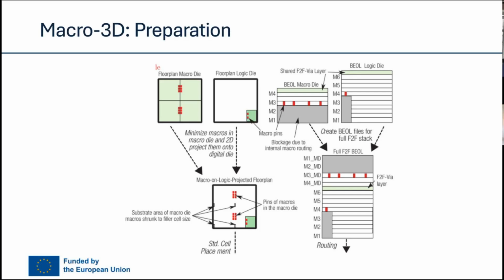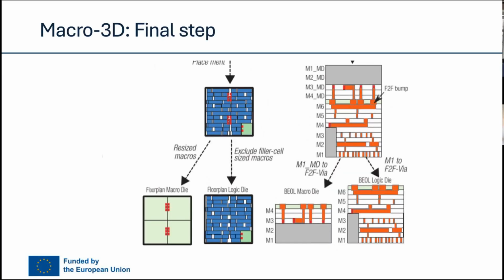Here you see this small red square from the top tier to the bottom tier. Once we have this substrate, to make sure that the tool can understand that, the trick that we are going to use is to have one virtual macro that occupies fundamentally the size of a standard cell and that has pins projected into the place where they actually belong to the larger macro.